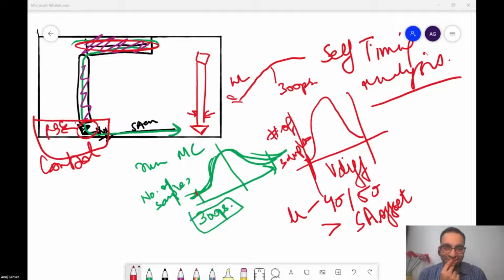So I understood that we need to create that worst bit line and worst word line column, and that would basically correspond to SRAM cell layout. But I was confused, like in SRAM cell layout, we need to optimize our figure of merits. So in this case, do we also need to optimize figure of merits for the 6T cell and then create the replica column, or just create a replica column and then observe?